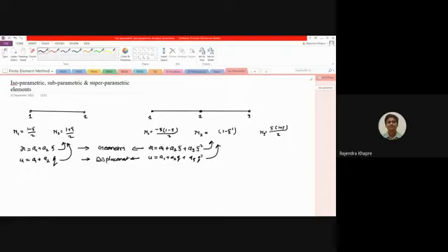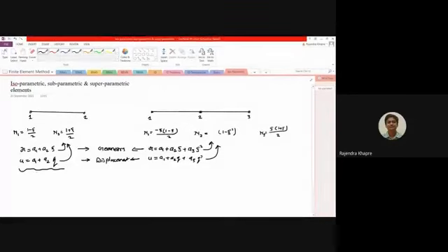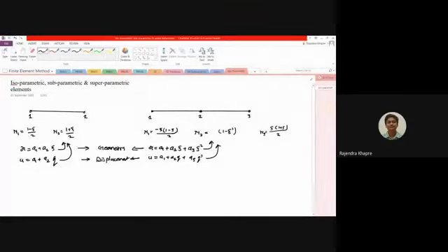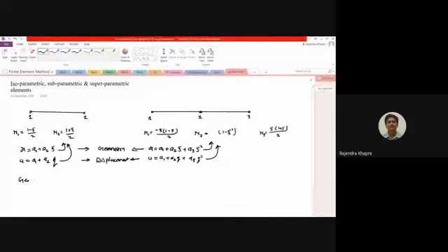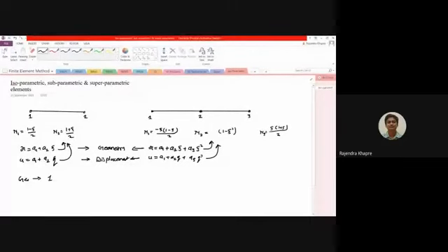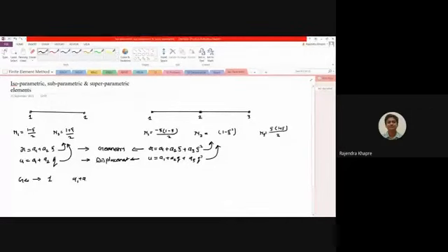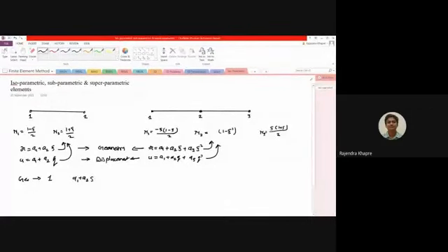Okay, so if you talk about just a 2D two noded element, let us say this particular element. For this particular element the order of the polynomial to define the geometry. Okay, so here what is the order? One order, because it is something like a1 plus a2 times xi. So here what is the power of xi? 1.